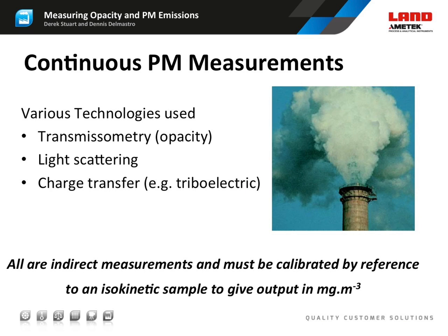Several measurement techniques can be used to detect the low levels of PM that are encountered in modern emissions measurements. In addition to opacity, the most common are light scattering and charge transfer. There are various implementations of charge transfer measurements, often referred to as triboelectric or electrodynamic sensors. These are very sensitive, but they can be difficult to use as they are also sensitive to parameters other than the PM concentration, things such as velocity and temperature. So these parameters have to be measured and a correction applied.